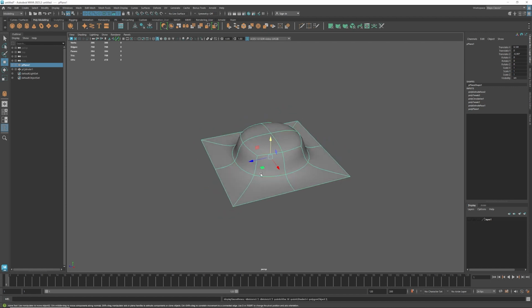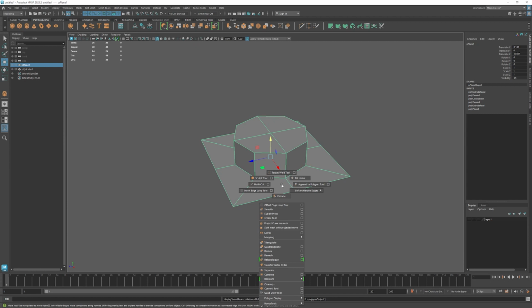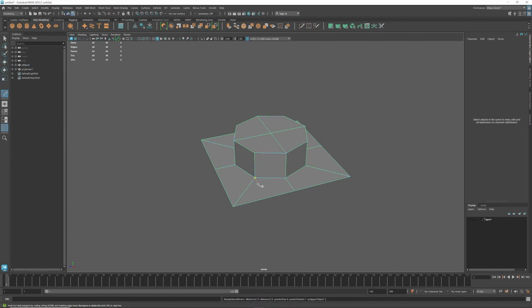But when I hit 3 on it, it basically turns into a kind of an ugly bump. So what I'm going to need to do is I'm going to need to basically go in there into the multi-cut, and I'm going to do a couple different things. And the first thing I'm going to do is I'm going to give it a little edge, and as soon as I do, it's going to round that edge around. Next thing I'm going to do is I'm going to add a little edge there, and that's going to basically create a little bit more groove.